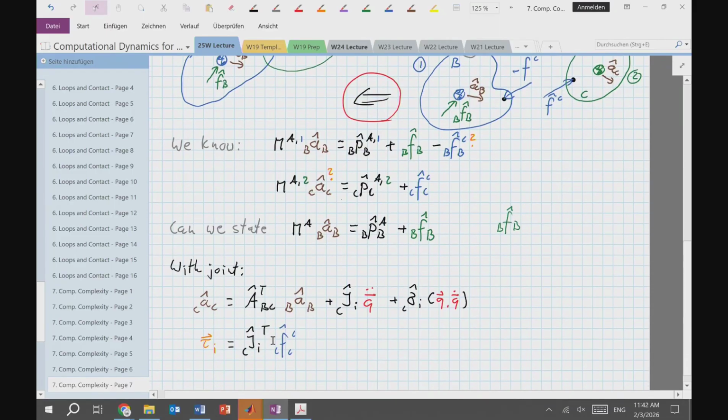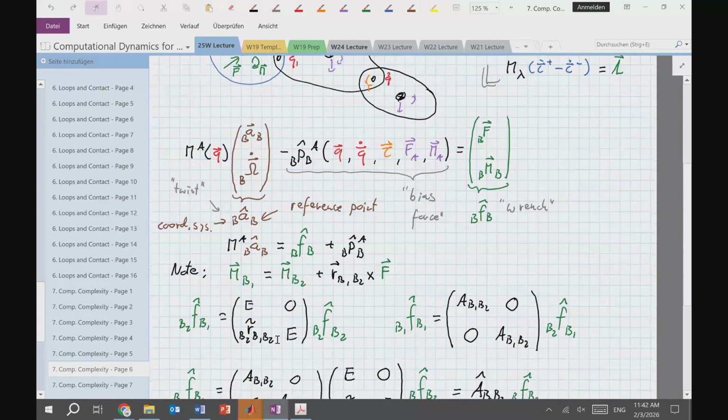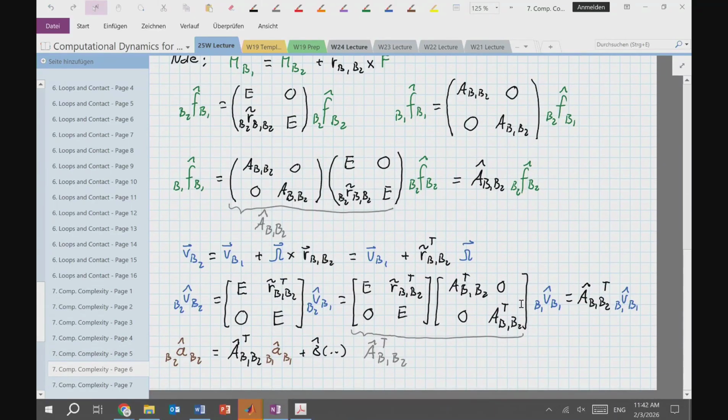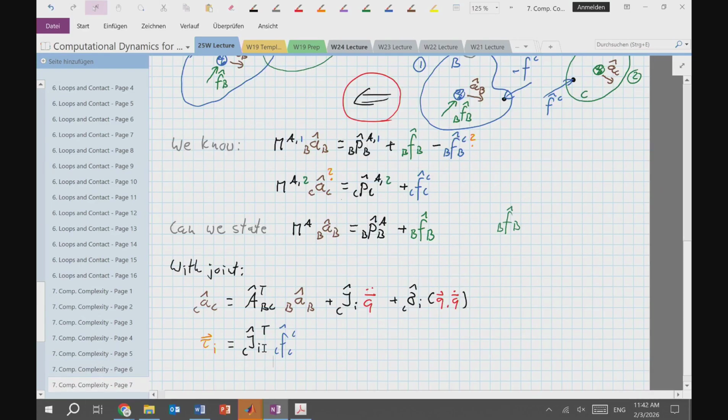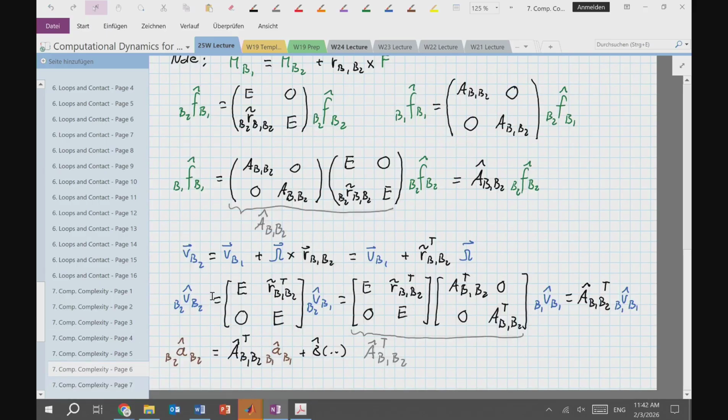We saw this when we talked about the recursive Newton-Euler algorithm. We've seen this in other instances where we do a Jacobian transpose mapping, where all I do is essentially a power equality over these quantities. About torque times q double dot: the power produced in this joint will have to be this force times the associated velocity. I didn't write down the velocity equation, but this is what we had on the previous page.